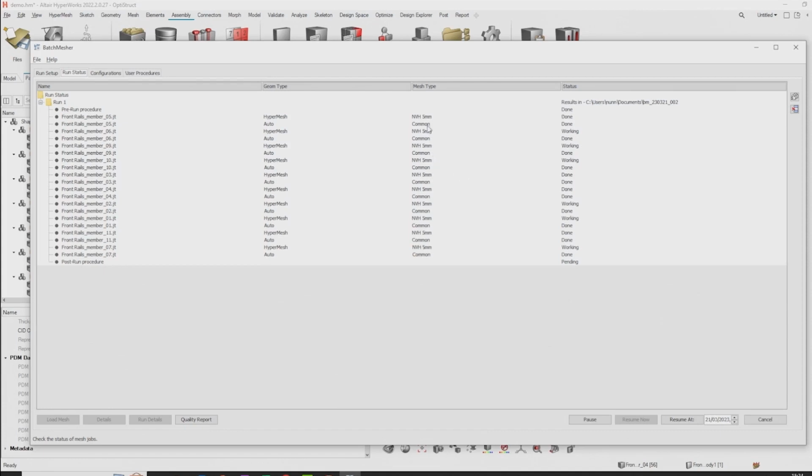The common representation is the mid-surface, and then from the mid-surface it extracts the mesh. The reason we split it into two is so that if you want to generate another mesh representation, we use the same mid-surface. So if we get some results back and the mid-surface was a poor extraction, we can clean it up. We can save it, we can submit mesh, but we can submit future mesh as well.